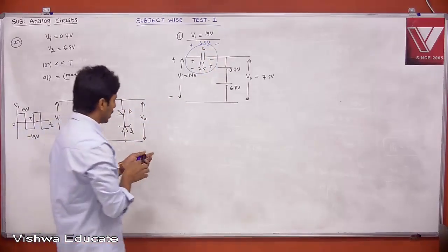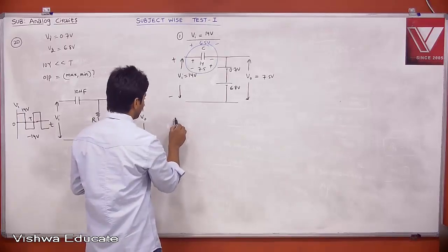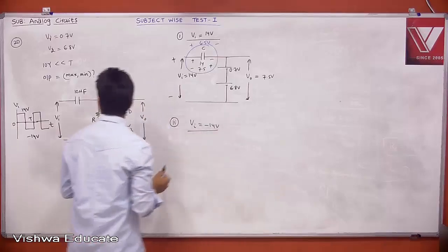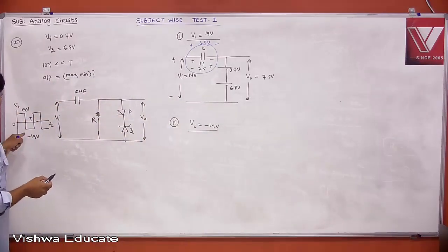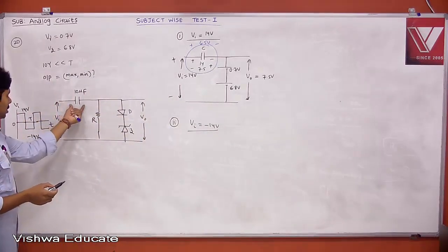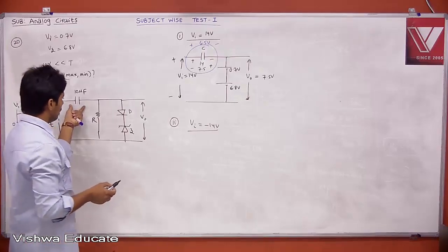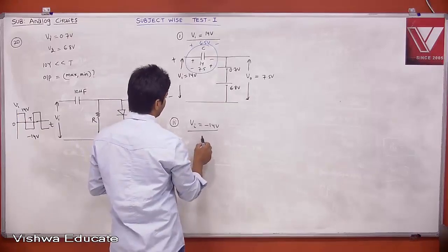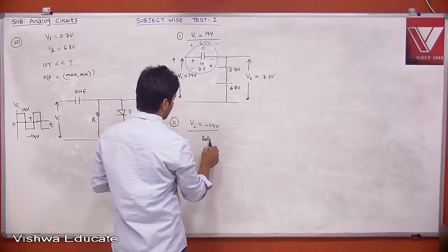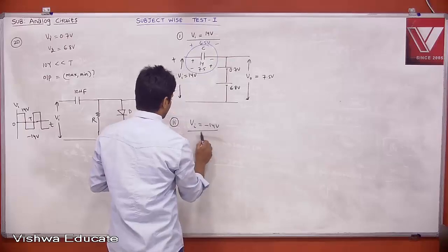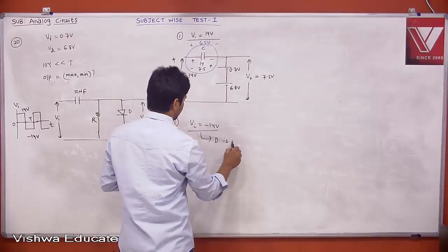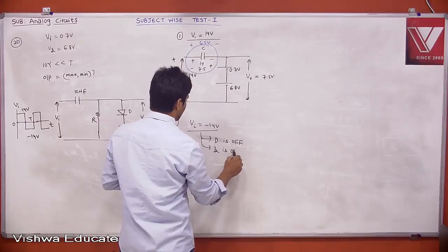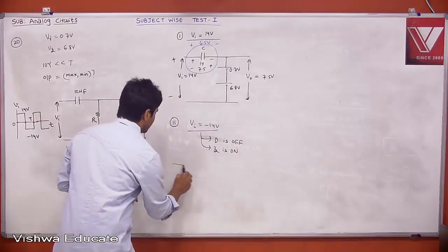Okay, fine. Now case 2, for the other phase of the input, Vi is equal to minus 14. Surely this is changing suddenly, but the voltage across the capacitor cannot change instantaneously. Then these two will be off. Your diode D is off, but your Zener diode will be on, but that doesn't matter for us. It is open. Then this is the circuit.